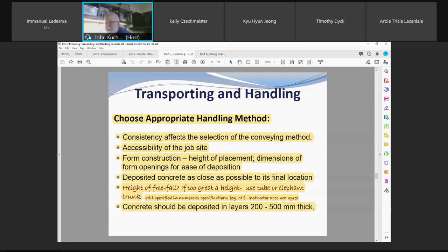Arena. And we were dropping concrete into a caisson that was 60 feet deep. We had a cage of rebar in it. We would back up 2 ready mix trucks, put both chutes down, and we'd let her fly. That concrete was dropping 60 feet. No segregation. The old way of thinking is that your concrete's going to segregate when it hits on impact. There may be some aggregates pinging off if you're hitting the cage of rebar inside the pile.